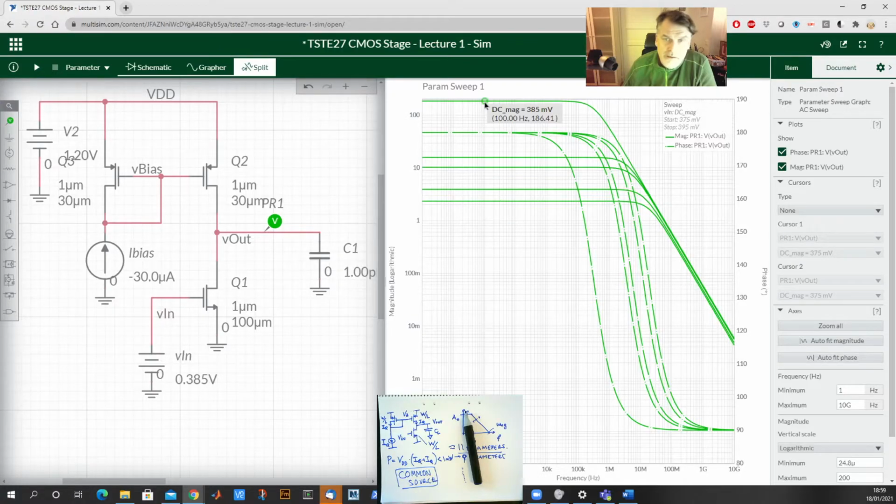So we see that the increase of gain happens when we increase the voltage to some extent, but then you get worse gain for higher input voltage. So this is some sort of sweet spot somewhere here. So 375 millivolts gives you worse gain, but also 390. So 385 seems to be some sort of optimum, which I have already tuned for.